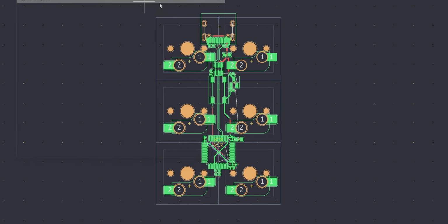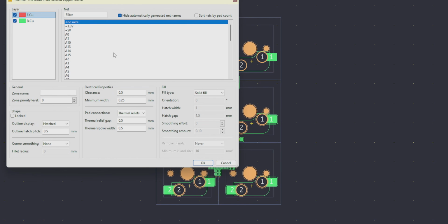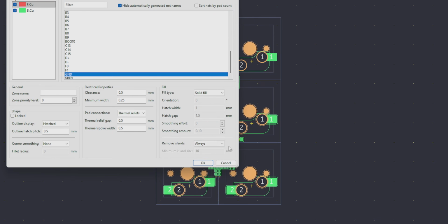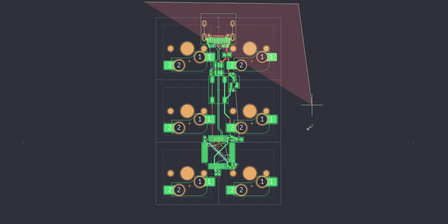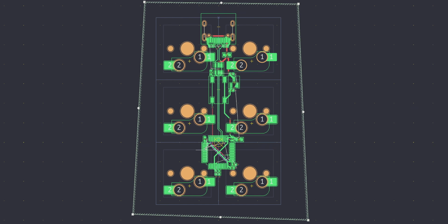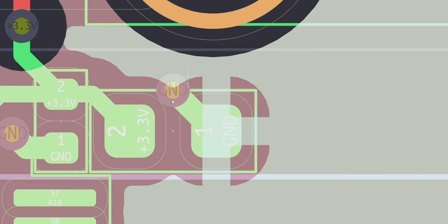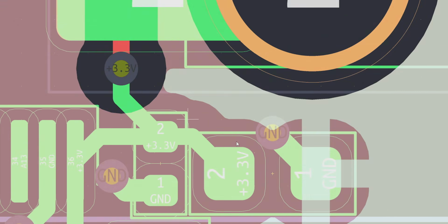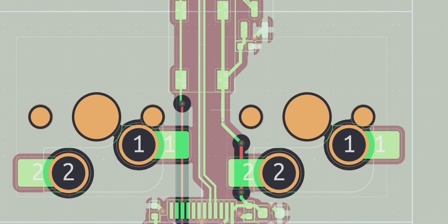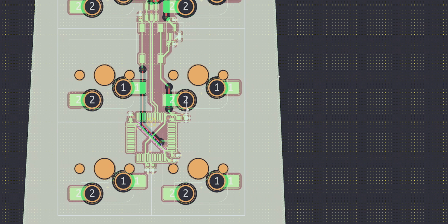Now, the final thing you want to do once you're done designing your entire board is create a filled zone. So we're going to select everything here, select both layers, and scroll down to make a ground fill zone, then click OK. We'll just go like this, double click to close it, press the B key, and you will see that everything here gets connected to ground. So this grounds out really solidly. Pretty much every via should ground everything out. And that's the overall idea of how this works for this schematic.